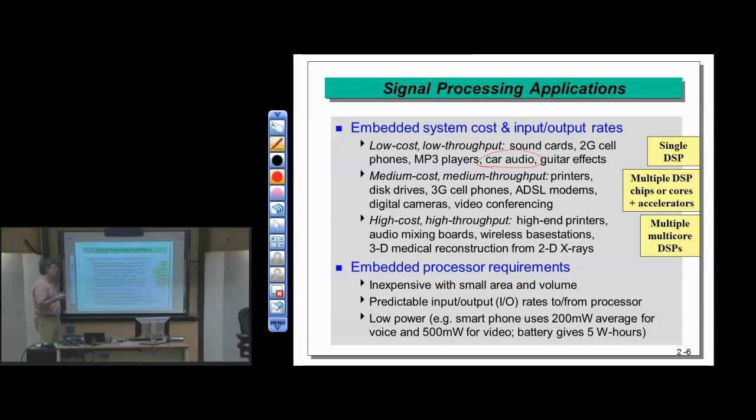In audio, what's a very common bits per sample? Like 44 kilohertz, that's a sampling rate, so 44 kilohertz, 48, 96 kilohertz, and so forth. How many bits per sample? 32. 32 is on the high end. 16, 24. 24 is about the limit of D to A and A to D conversion today over those kinds of sampling rates.